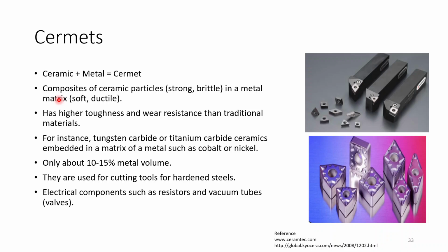So these are composites of ceramic particles, which are strong and brittle, in a metal matrix, which is soft and ductile. And this metal matrix is only up to 5 to 10 volume percent. It has very high toughness and wear resistance compared to the traditional materials.